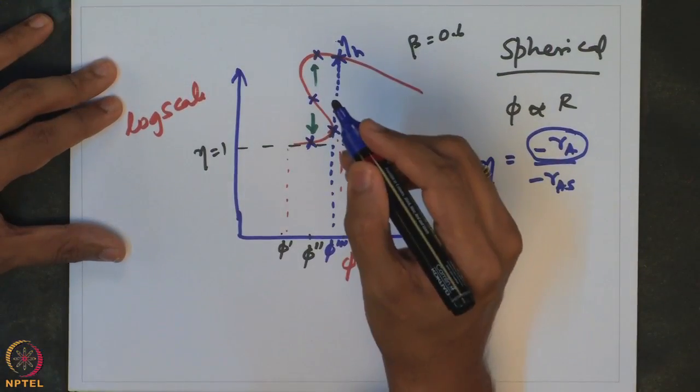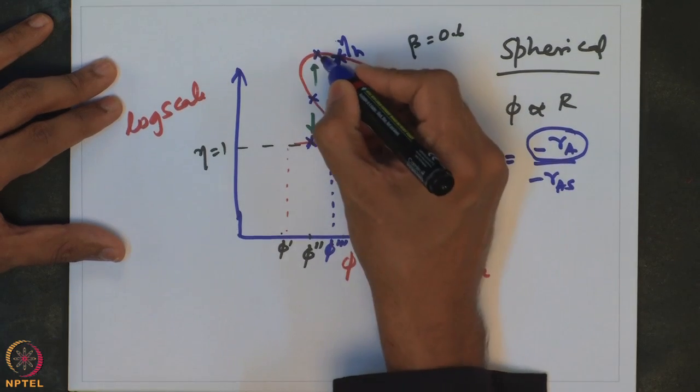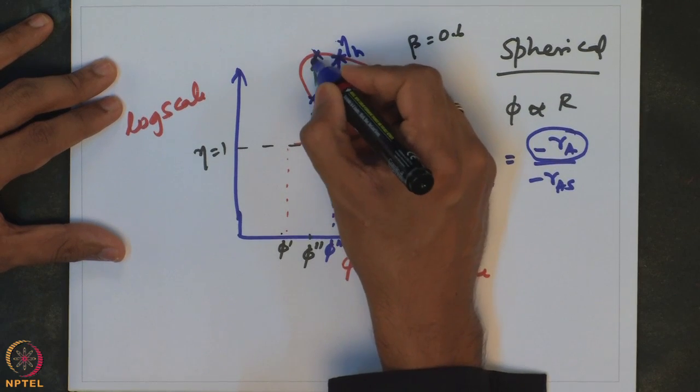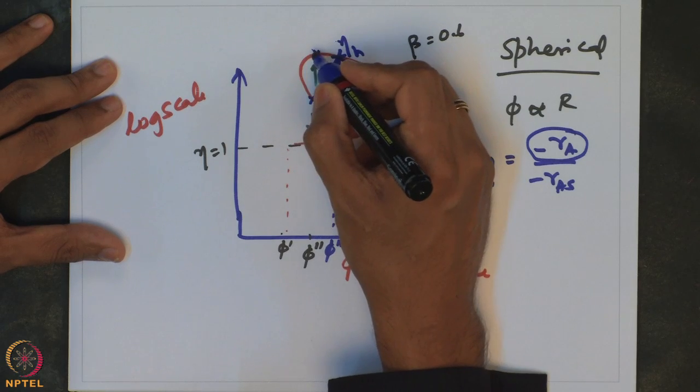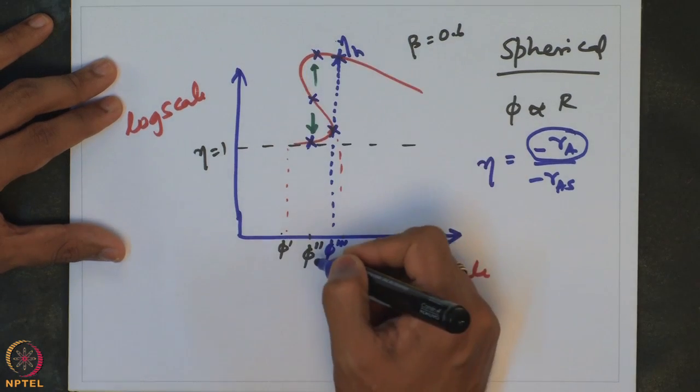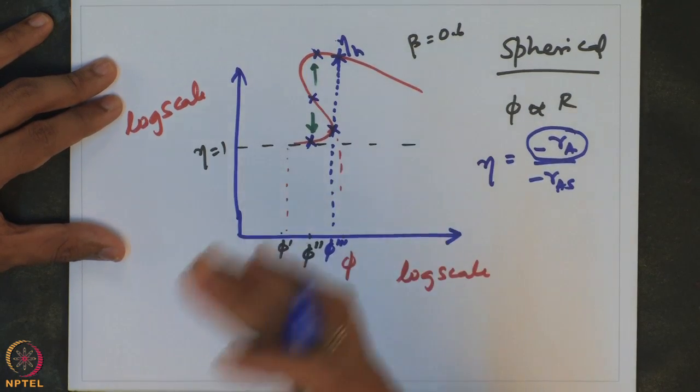So, observing the presence of these three steady states and taking a decision as to where it has to be operated is critical. To increase the productivity, one may want to operate the reactor under the highest possible effectiveness factor for a given Thiele modulus, because that is going to have a very high rate at which the reaction can happen, and that will increase the productivity, which directly controls the economy of that particular industry.